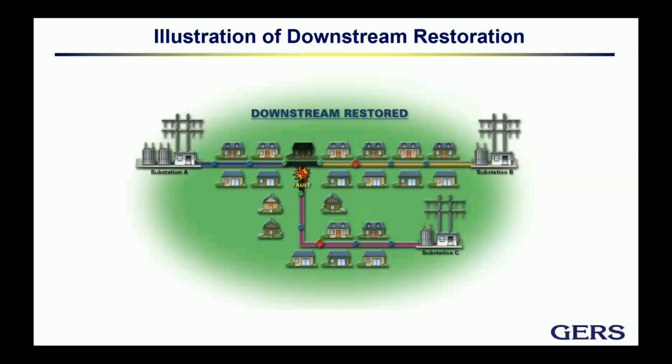What type of trouble? Okay, number one, we cannot overload them. Number two, we cannot bring harmonics that can create resonance conditions with capacitors, for example, that they have. Number three, they can, for example, exceed the ampacity of the cables, etc. We will discuss this in a bit.